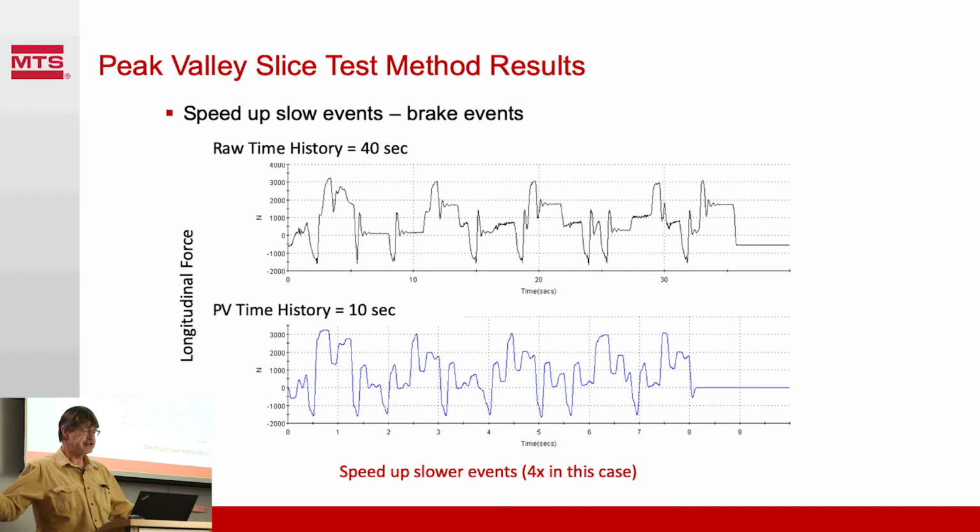We don't need to take 40 seconds to play that back. The fatigue damage occurs in a matter of a few seconds. So in this case, we can literally slide this stuff closer together, maintain the same overall amplitudes and fatigue damage, and play it back, in this case, 10 times faster or 8 times faster than real life.